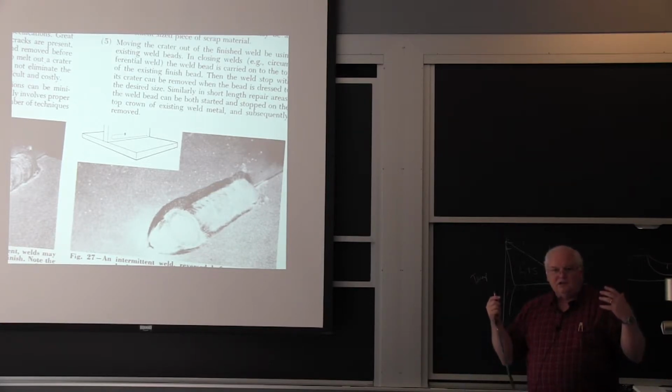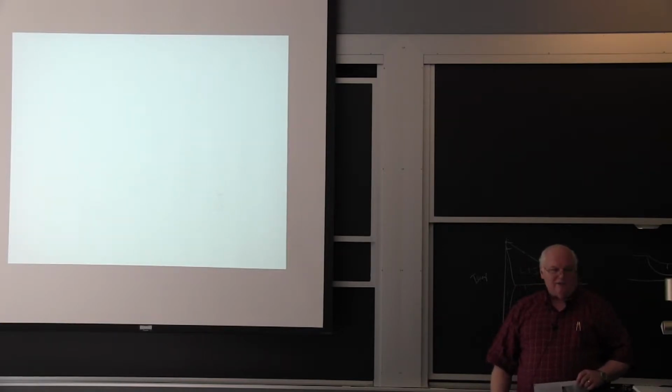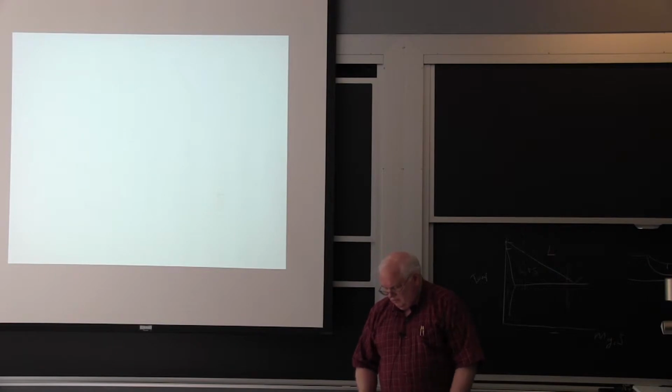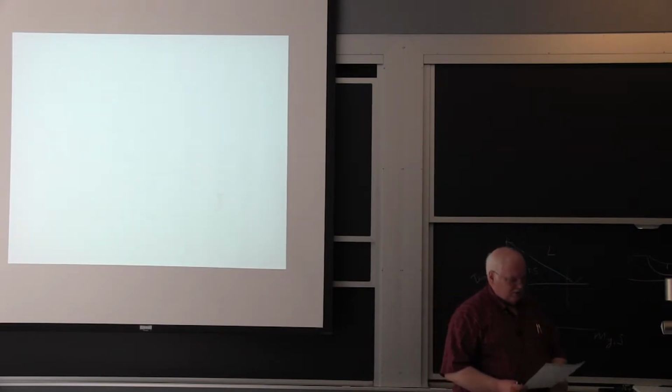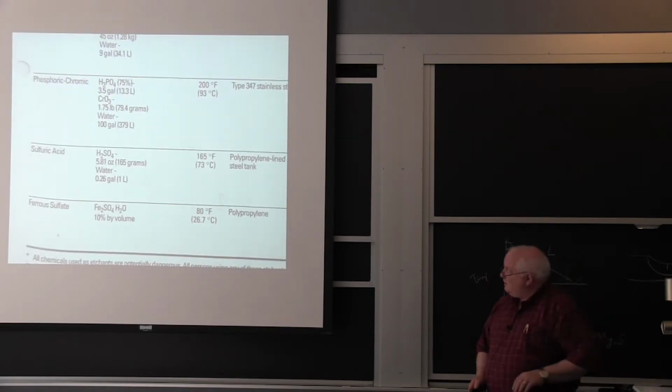Most of these guys figure, I can weld steel, I can weld aluminum, I can weld titanium, I can weld zirconium, I can weld anything. Well, maybe not. Okay, there are techniques with each material. Okay, another problem with aluminum is it tends to form an oxide. And you got to clean off that oxide.